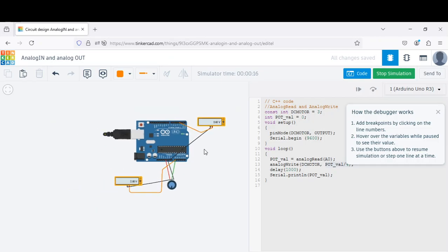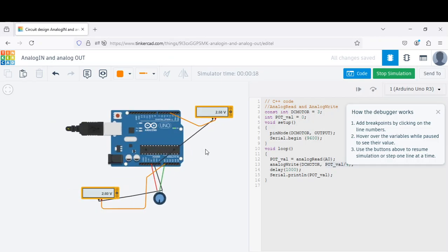So that's it. Like analog read, analog write, how do you manipulate the value when you read it inside. So what is the actual analog voltage when you actually read? It is nothing but the decimal number multiplied by 1 LSB, where 1 LSB is 5 divided by 1024. Thank you.